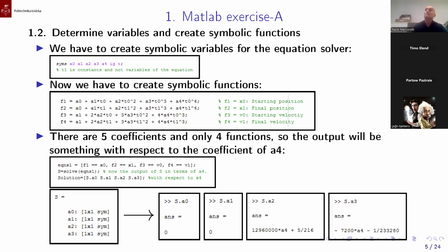Okay, let me try to explain this part of the software. Do you remember syms? I don't know if I told you about syms. This means in MATLAB you define after syms this element here, basically 5 coefficients starting from A0, which we need to characterize the polynomial, and then we will see what is the parameter t, which is the time.